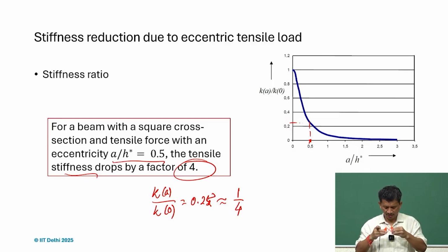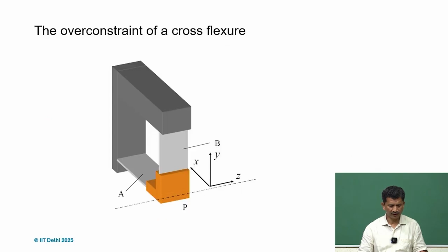Yes, we have a problem if it's a compressive load, so it's a slender part, so the buckling will come into picture, and as it deforms, that load capacity will get reduced. So it's very important to understand what kind of loading should be there and how it should be applied. So be aware of that.